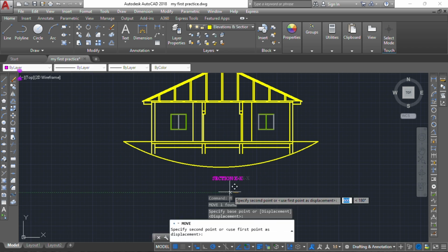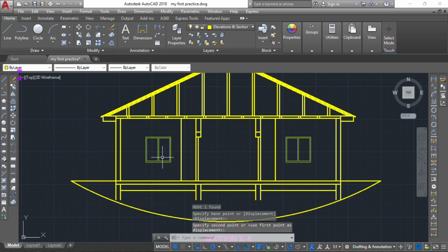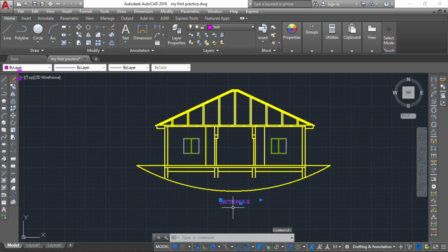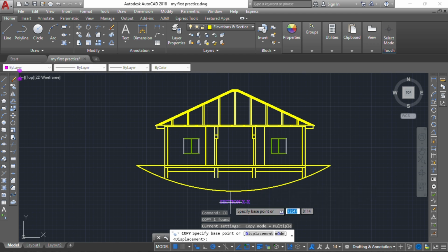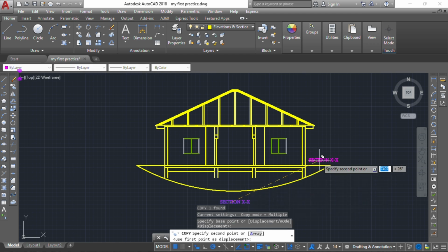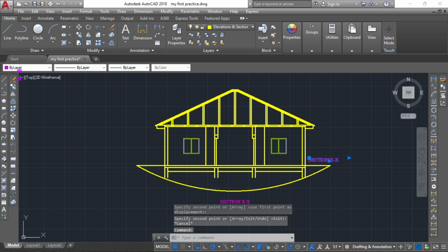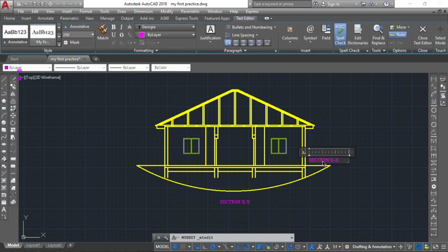And then let us section them. Our walls that we section, our blockwork, should be indicated, right? It should be indicated that it sections our ground level here, and everything also should be indicated. So let's just copy this, bring it here, and indicate this as our ground level.